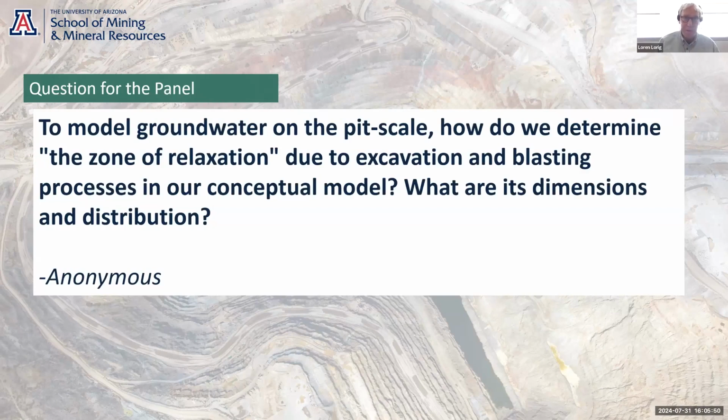So, for example, at Bingham Canyon years ago, they had a microseismic network. They back analyzed it to show that there had to be a zone of lower seismic velocity around the pit, and you can infer that very well that that's a zone of relaxation, because the joints have opened up, the seismic velocity has dropped.